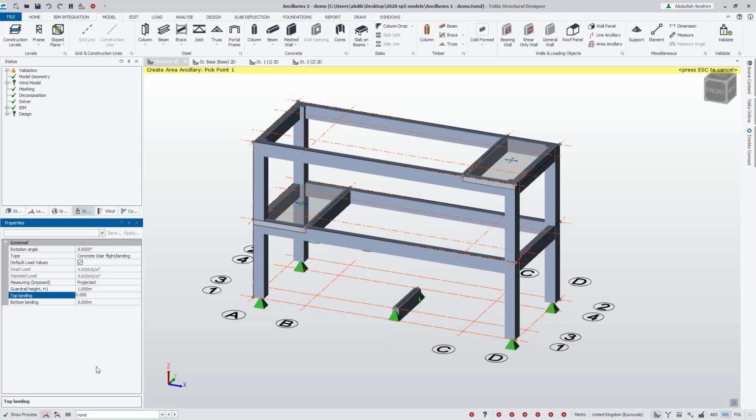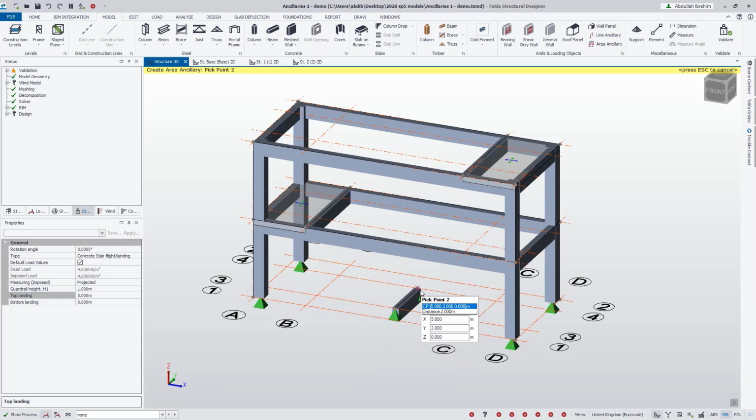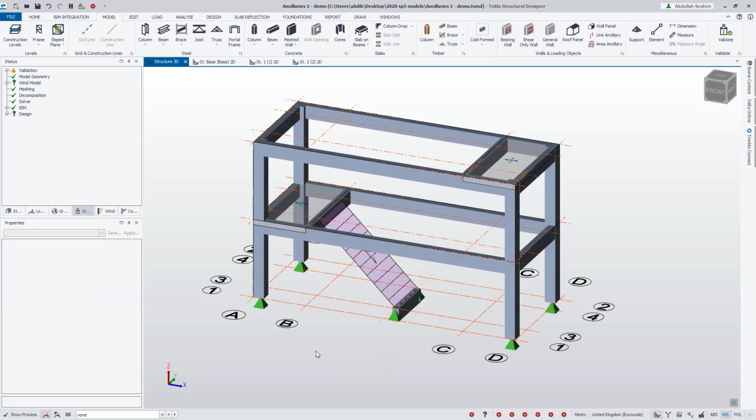We will now define the geometry of the ancillary load. To do this, we simply click the corner points where we're going to be modelling those ancillary loads, which are the 2 points at the extreme ends of the beam at the base. I'm just going to snap these onto the intersections over here. I'm going to double click on the final point to complete the insertion of this ancillary load. Just going to double right click to escape that.